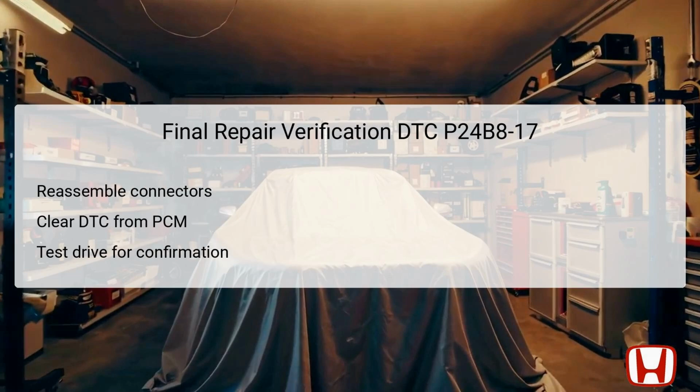After completing the necessary repairs, the final verification of the repair process for DTC P24B8-17 is imperative. Begin by reconnecting all previously disconnected components, ensuring that they are secured and properly seated. Next, clear the DTC from the PCM to reset the system and eliminate any error codes. Following this, it is advisable to conduct a test drive under various operating conditions to confirm that the issue has been resolved and that the DTC does not reappear.